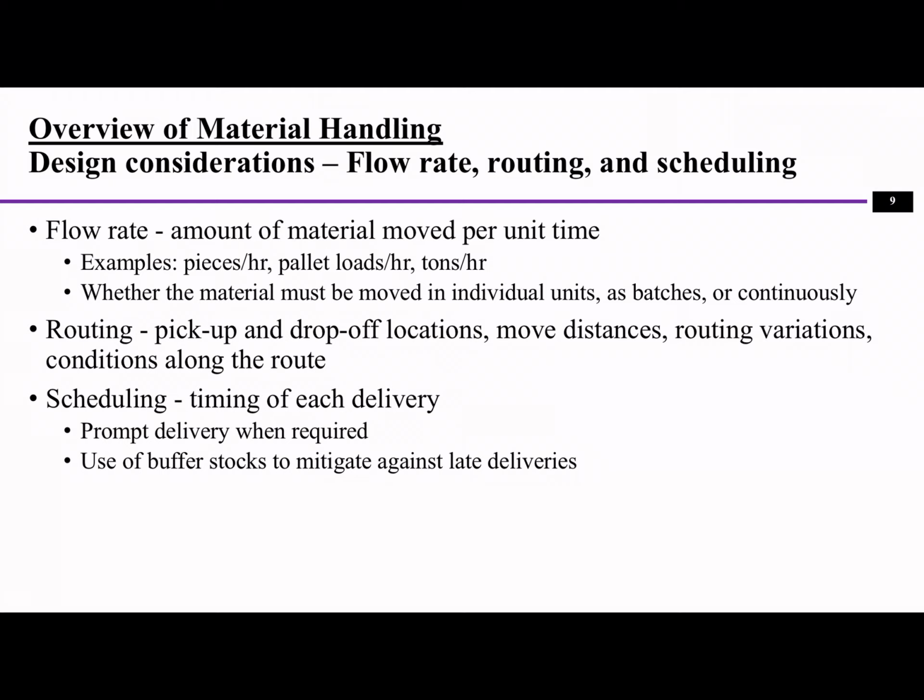When you are designing this kind of material handling, you have to think about trafficking. If there are a lot of AGVs or equipment going on, or transportation trucks going on, you have to think about what is the length of that, and how long does it take to transport materials from one station to another. Then that may affect the whole overall production cycle time. Some of the methods we have, if there are some bottlenecks, we talked about that before, so we can use some buffer stocks to mitigate the delays.